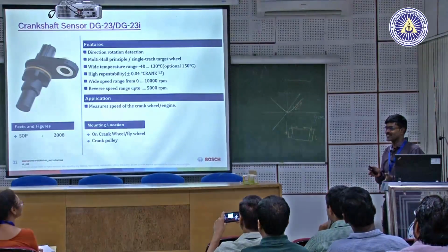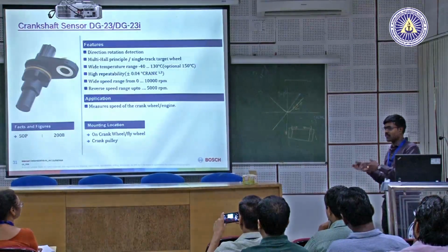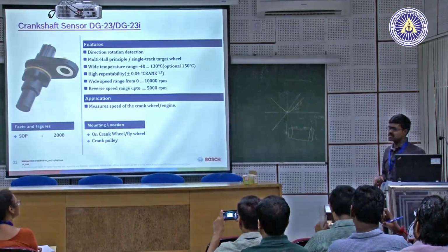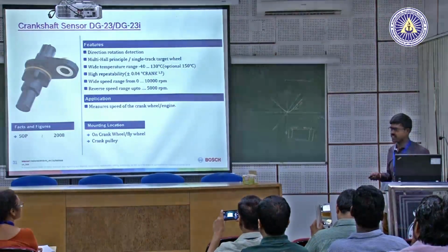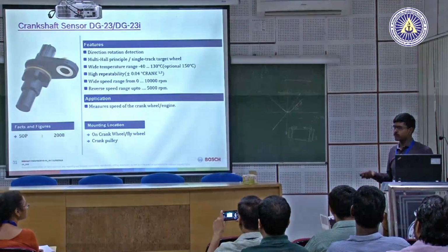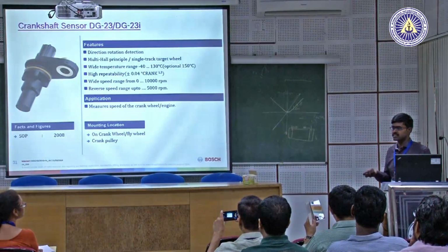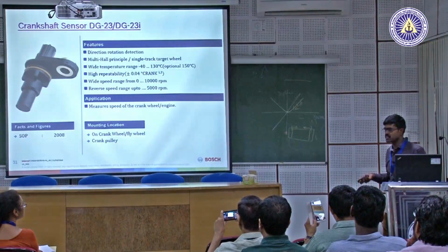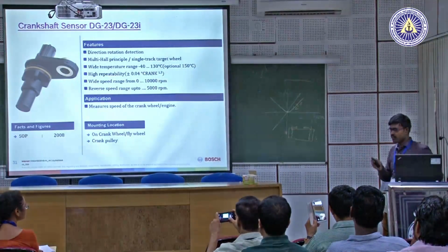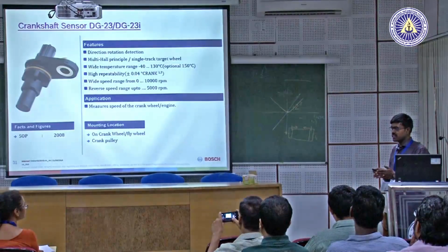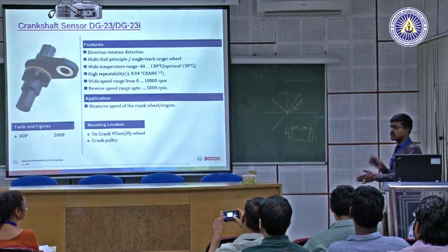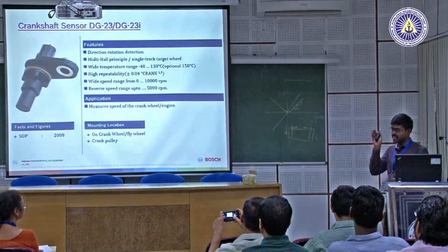They will have to choose whether they want to be cost effective with the analog sensor. Till now all the vehicles are running with it, but you would have known about the emission legislations which are going to be imposed in 2020, that is BS6, which is Bharat Stage 6. For those applications they need the accuracy for calculating the position of the cylinder to synchronize with the speed of the engine to inject the fuel quantity for effective combustion.